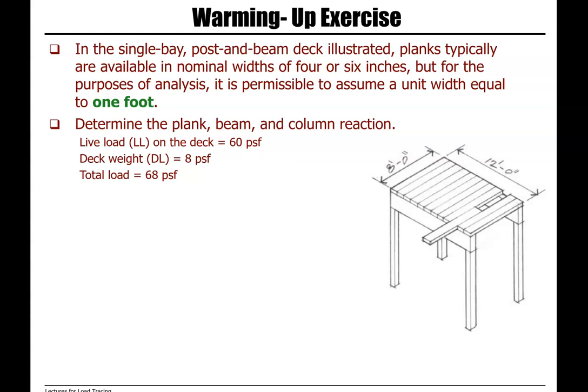Warming up exercise. We have a single bay, post and beam deck consisted of planks. Planks typically are available in nominal width of 4 or 6 inches, but for the purpose of analysis, we will assume a unit width equal to 1 foot.